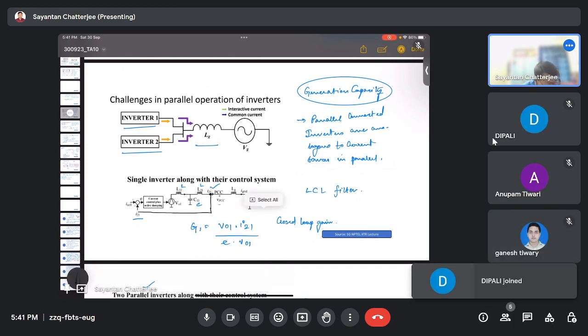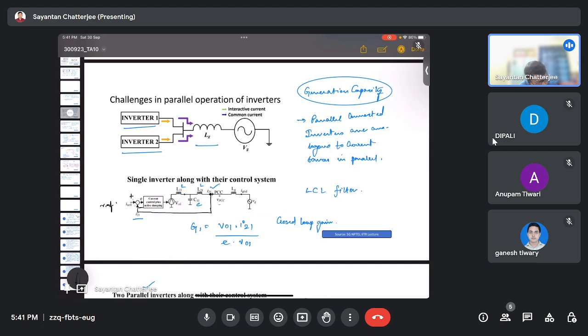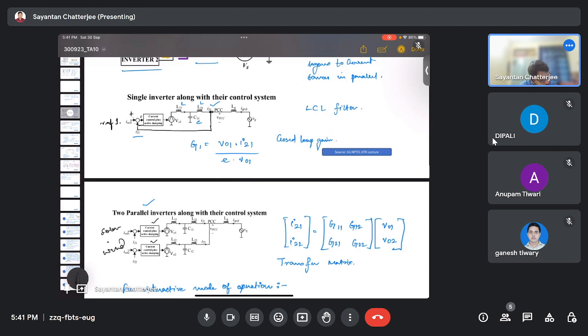This I21 is given as feedback. Now, this is the control plus minus gain, the summing block, with positive and negative inputs. This is the reference set point value for converter 1, and this is again for converter 2. These two reference set point values should be similar, so that they would be feeding the PCC with the same current I21.